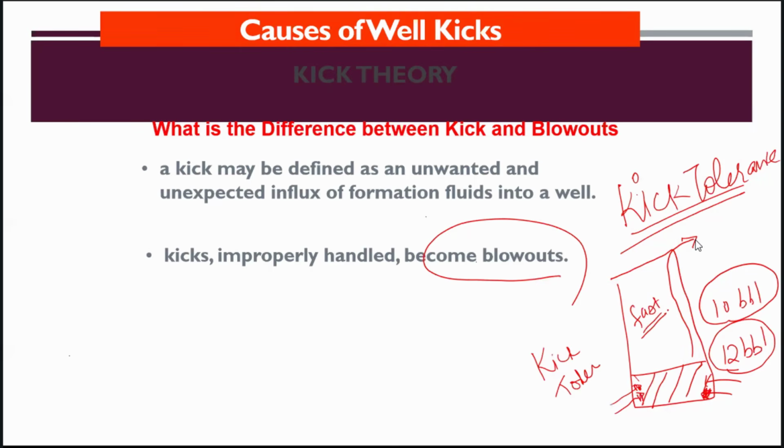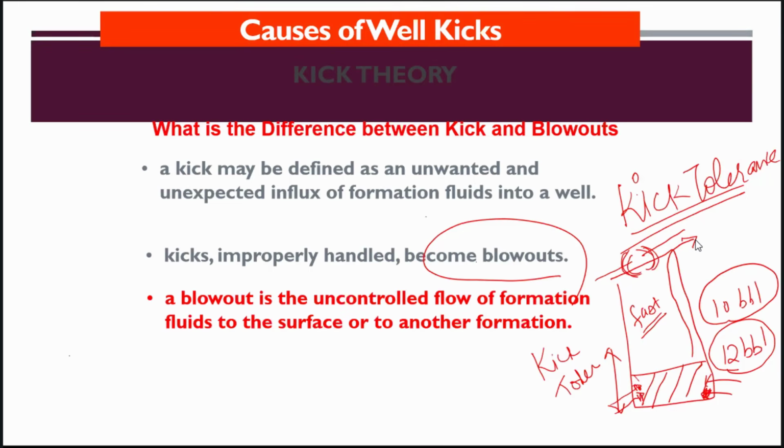If we respond very fast and close in the well on time, then we get less volume. But if we take time to recognize the kick, if we take time to recognize the warning sign, then we will get a big volume of kick, maybe higher than our kick tolerance, and it will be difficult to manage and it can become a blowout also. So a blowout is uncontrolled flow of formation fluid to the surface or another formation.